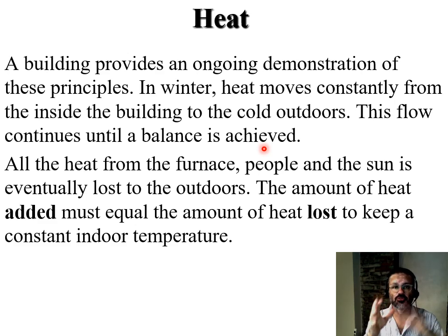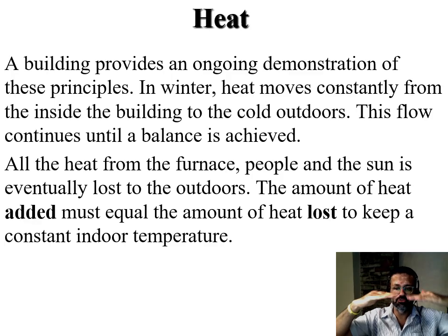So heat goes to where there's no heat. What you want to do is capture the heat from the furnace, the people, the sun, and other things, that's going to the outside. If you want to maintain a steady temperature inside, the amount of heat added must equal the amount of heat lost. That's what you're trying to do, create that balance.